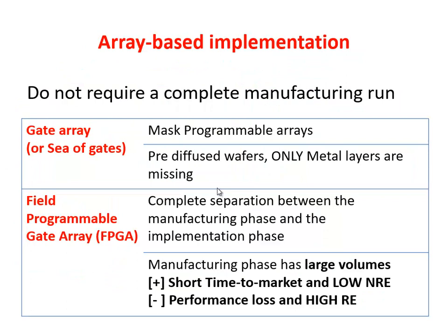Okay, let me consider now the other part, which is the array-based implementation, the part which does not require complete manufacturing. You remember there were two different possibilities, the gate array and the field programmable gate array. As I mentioned, in the gate array, the front end, so the single transistors, have been already fabricated.